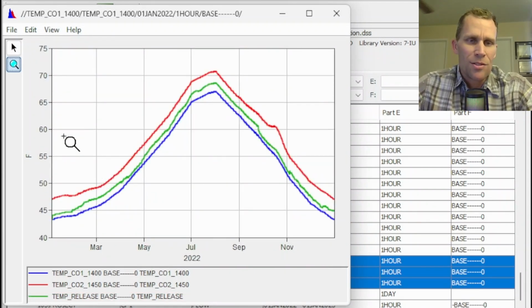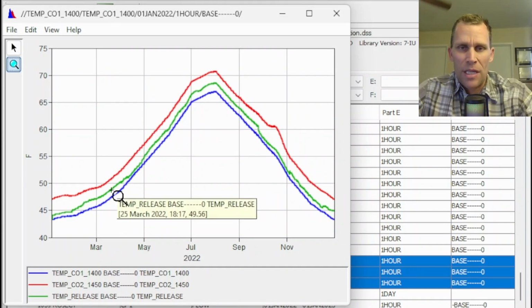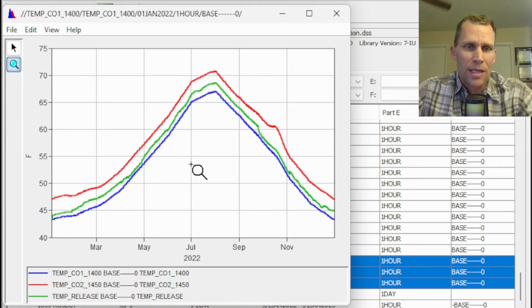So anyway, this is just a quick reminder of one more example of how to use ResSim and state variables. In this situation, what we did was we created the water temperature profile over the course of the year, and we calculated what the water temperature was based on all of our assumptions of historical data and depth gradient temperature changes, and of course the inflow and the guide curve to give us a lot of analysis, which was easy to do using state variables in ResSim.